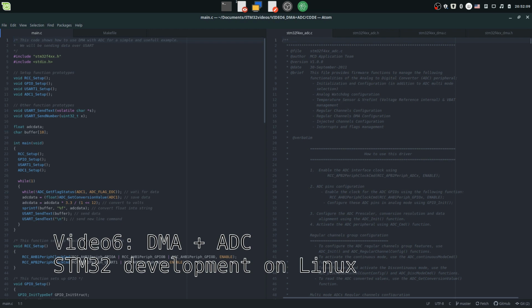Today we're gonna talk about the DMA as promised before. We're gonna show you how the DMA works on the ADC example. What the DMA is, it's a direct memory access controller. This is a peripheral inside your microcontrollers that copies data from one part of the memory to another, or from a peripheral to memory and vice versa.